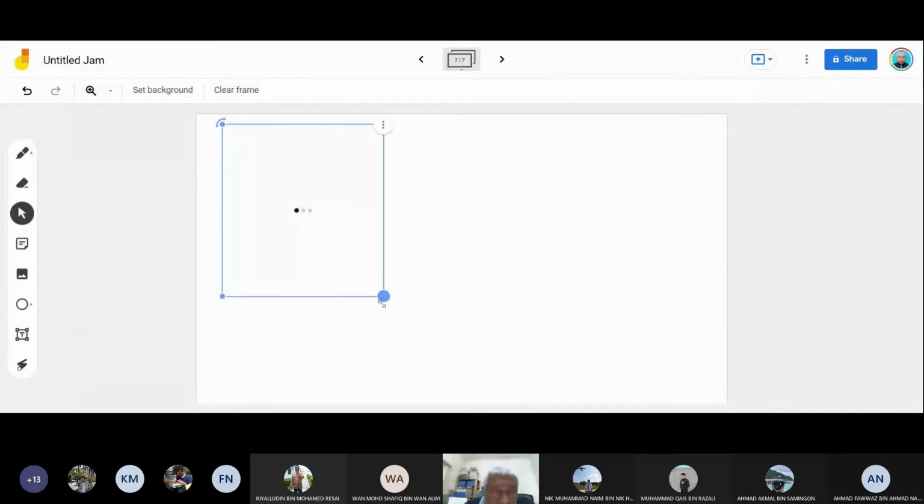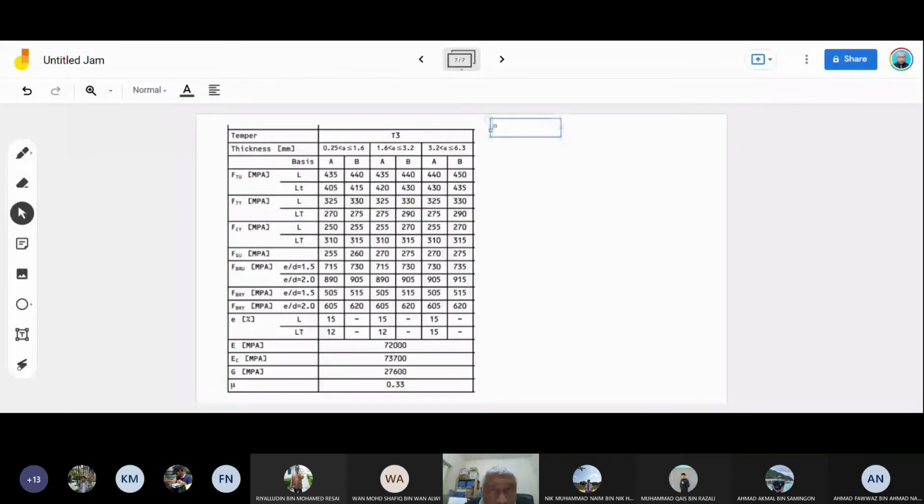so this is typical material allowables. We call this material allowable, and it is always given by the OEM in the SRM, or from the material handbook, MIL-HDBK-5, which has all types of material listed in the handbook, or the material allowable will be in the handbook, or you can get it from the SRM.